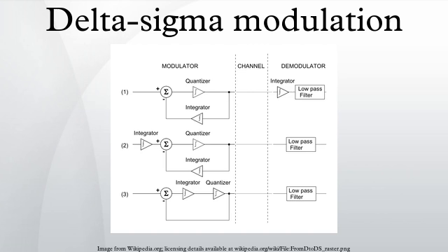3-level and higher quantizer: the modulator can also be classified by the number of bits it has in output, which strictly depends on the output of the quantizer. The quantizer can be realized with an n-level comparator, thus the modulator has log2 n-bit output. A simple comparator has 2 levels and so is a 1-bit quantizer. A 3-level quantizer is called a 1.5-bit quantizer. A 4-level quantizer is a 2-bit quantizer. A 5-level quantizer is called a 2.5-bit quantizer.